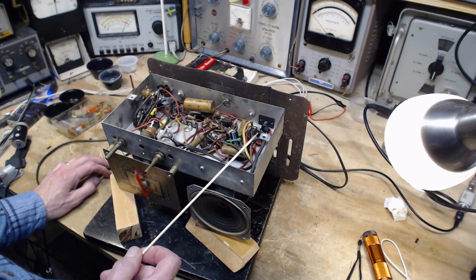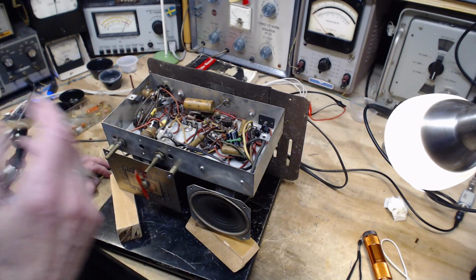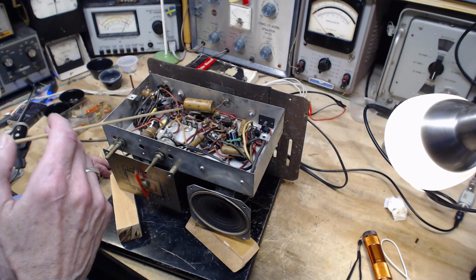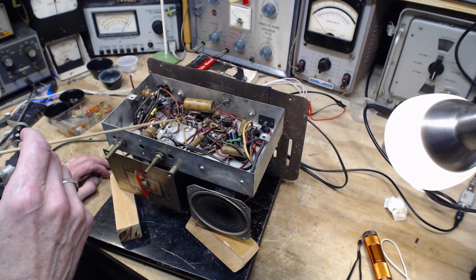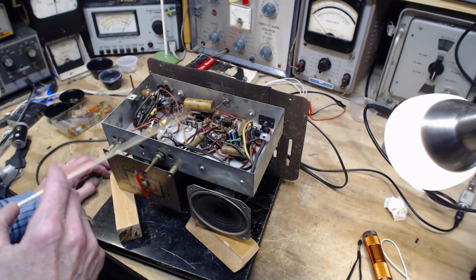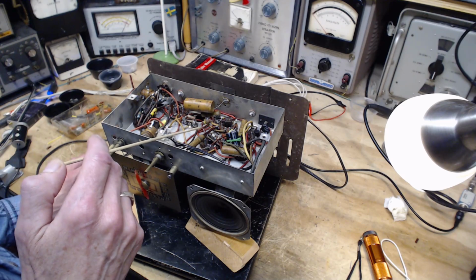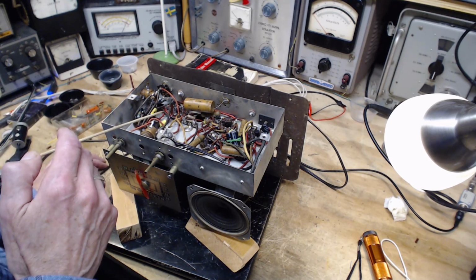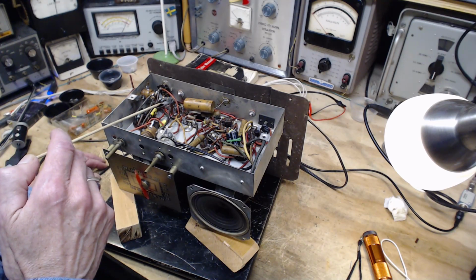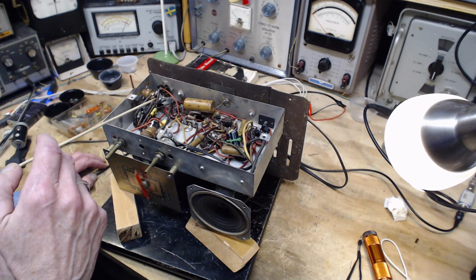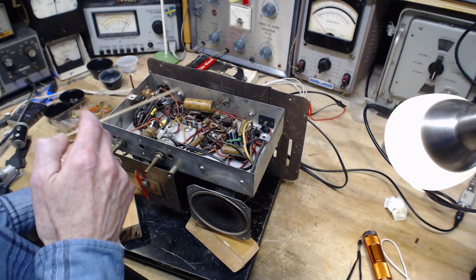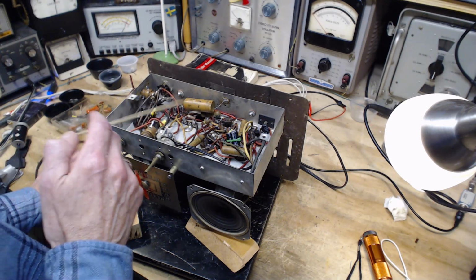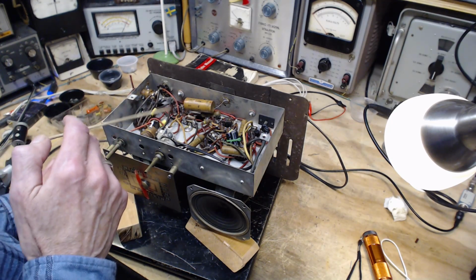Beyond this very large resistor, and in this radio it's a whopper of a value, I think it's 11 megohms or something, it's very high. The circuit can be considered to be a very high impedance circuit. In fact, it's almost nothing more than a piece of wire running around inside the radio. Yeah, it's connected to some grids, but it's not really going anywhere.